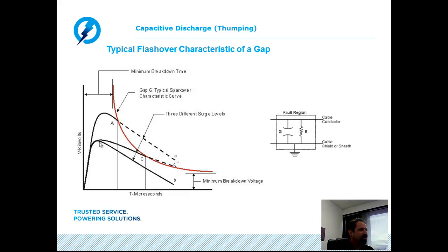Now, when we move to thumper B output, we see that thumper B has plenty of initial voltage, but perhaps the limitation is that the capacitor inside this thumper is very small, and in essence we don't have enough energy to overcome the combined capacitance of the cable we're feeding into.